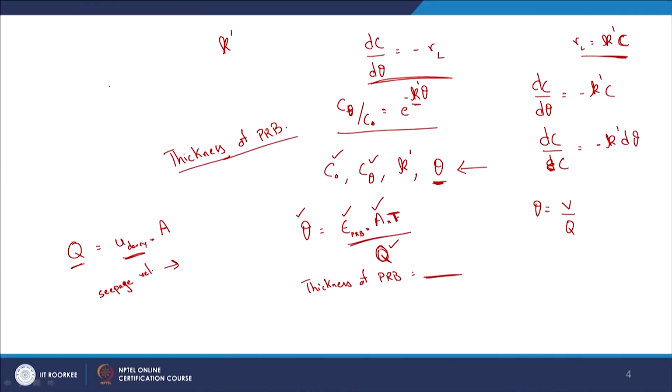You can think of Darcy's velocity as, this is in the context of groundwater obviously. So, let us say the average velocity of that particular fluid for that particular cross sectional area, right. So, if this is the side view and the groundwater is flowing through this particular system and this is my cross sectional area, or let me draw the other side view, and the groundwater is going in this direction towards the screen, or into the screen, let us say it is going into this. So, if this is the cross sectional area, that is what I am talking about here, the area of this particular system, cross sectional area times Darcy's velocity will give you the flow of groundwater, right.